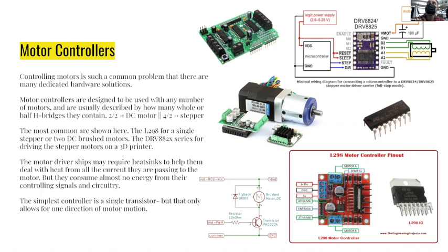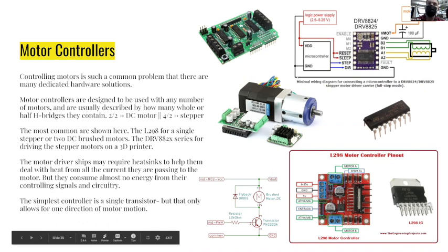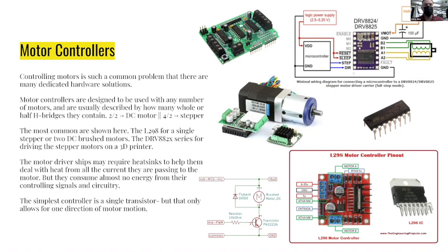But little stepper drivers like this are really, really helpful. They let you drive motors either forward and backwards or drive steppers with very precise step control. So they're totally cool pieces to have control. And the fancier, newer chips of these give you feedback, so your system can tell if the motor is stalled, or you can tell if it's drawing more current than it's supposed to be doing. There's all sorts of weird sensors and things that get baked into the brand newest ones of these.